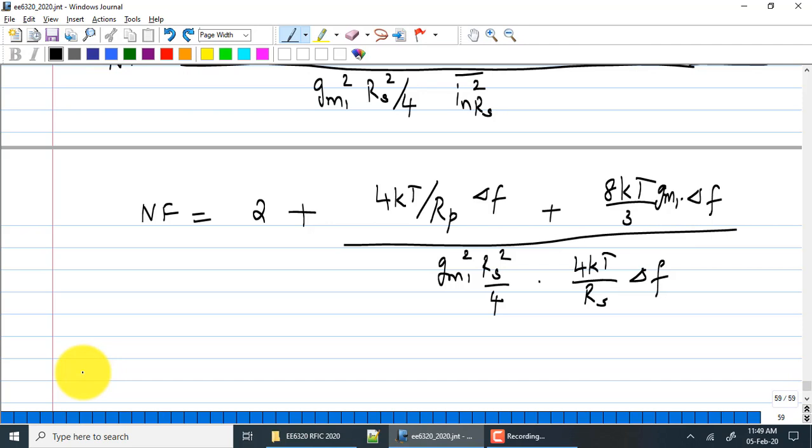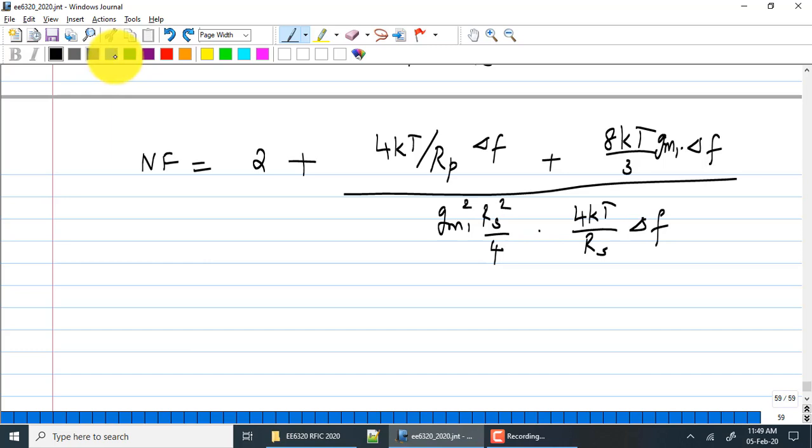Why don't we include flicker noise? Because the assumption is that RF frequencies are in the hundreds of megahertz, if not gigahertz range. Normally, flicker noise operates from very low frequencies, microhertz or millihertz, to about tens of megahertz. Okay, please simplify this, just to make sure I'm also not making any mistakes.